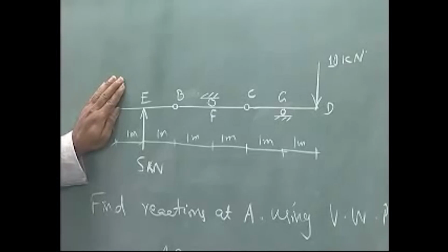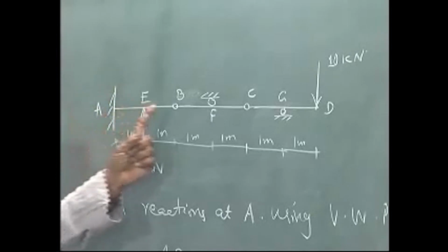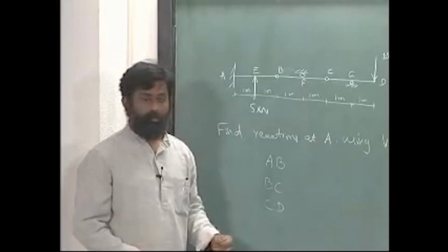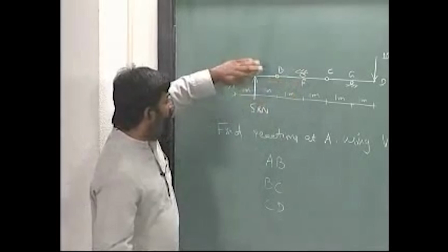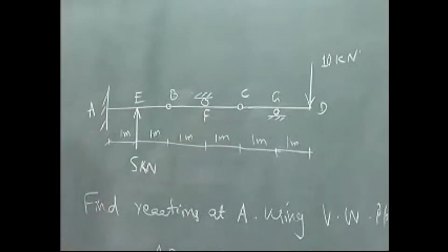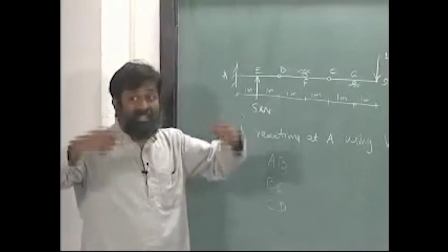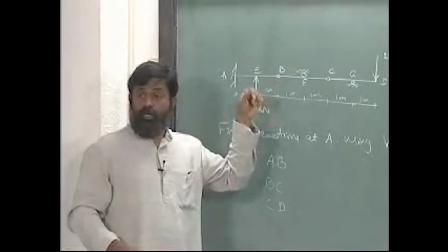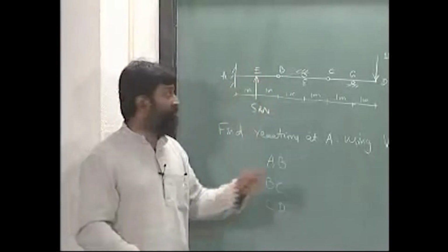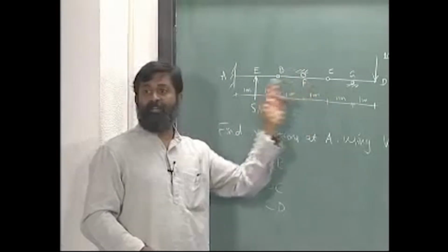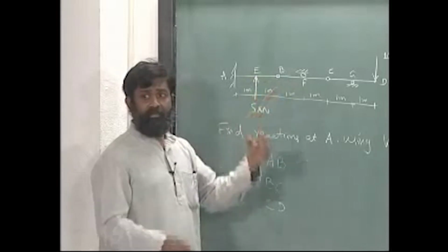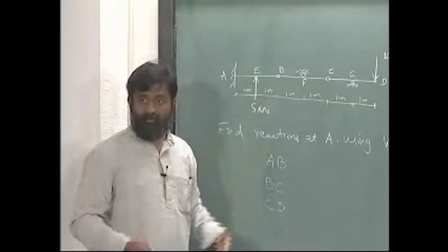Let us come back to this A later. Between AB and BC, what do I know? The displacement, supposing I fix AB, the displacement of B of BC is fixed, alright. So it offers a constraint at B, whatever is the displacement of AB at B, it is the same displacement of B at BC, correct, and therefore can it rotate between them? The rotation between them is allowed, right.